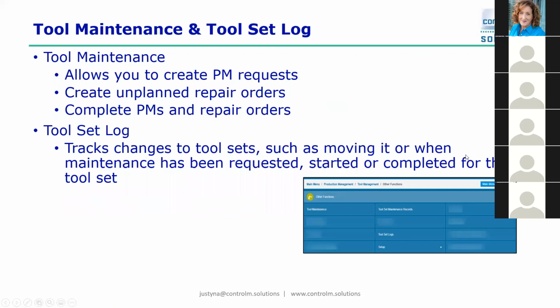All right, so tool maintenance. Tool maintenance is an essential part of maintaining your tools throughout their life, be it through random repair orders or scheduled PMs. In my demo, which we will go into Plex shortly, I will show you how an operator can request an unscheduled repair right from the control panel.